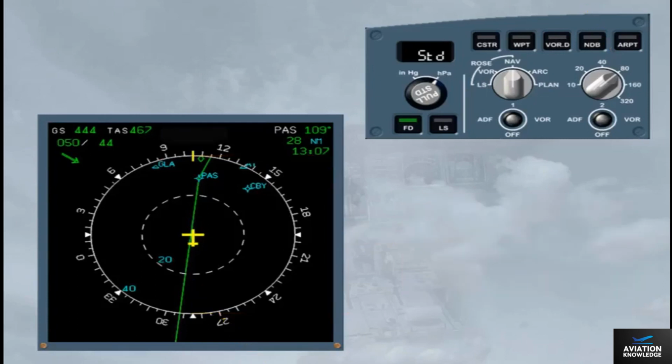The information contained in the top right-hand corner of the display relates to the waypoint. The information is track to waypoint, distance to go, and ETA, estimated time of arrival at waypoint. In this example, the waypoint is Papa Alpha Sierra, and is also displayed on the map view. Note: as the waypoint is a tuned navaid, it is in blue instead of in white.